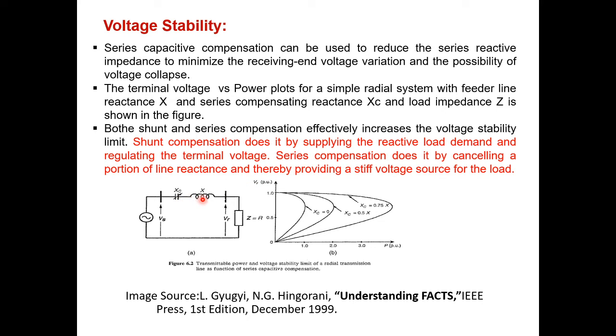Originally this one is X. When I place one capacitor here, the entire effective reactance reduces, and that improves the voltage. Within the limits of voltage, we can maintain it here. That is nothing but the voltage stability point of view. That is one more application.